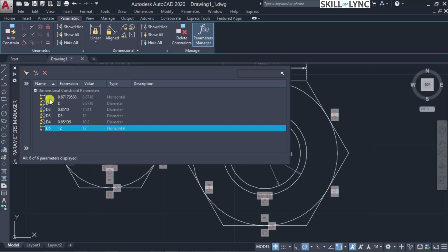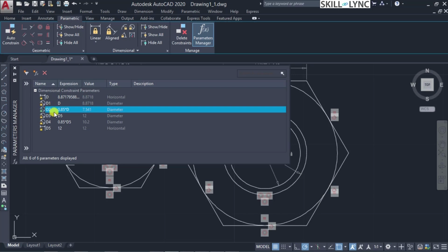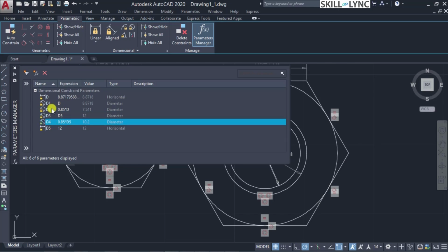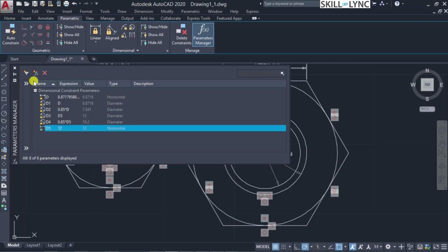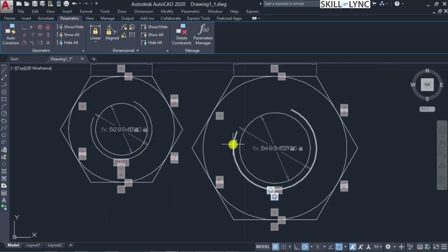Okay, so the numbering has been made based on the previous dimensions that are available. If you could recollect, the base was D and we had selected D1 and D2 to represent the other dimensions, and AutoCAD subsequently allocates the next dimension numbering sequentially, but all the parameters that are already constrained get applied to this. So this is how you can use the dimension constraint and then save it in the drawing, so that you can modify the drawing based on the different requirements that you have. So this summarizes the dimension constraint that you can apply onto your drawing.